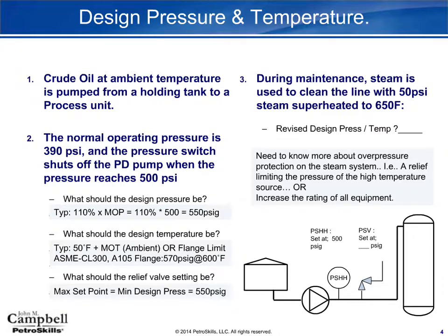So these are issues that we regularly get into with our process engineers, trying to better understand what is the design pressure and temperature. And I think most people can connect and realize how important having this clearly defined is. The system design pressure and temperature is going to affect not just the piping design, it's going to affect that pump, it's going to affect valves and valve seals. So having this information up front and defined clearly is very important for us as it moves forwards.